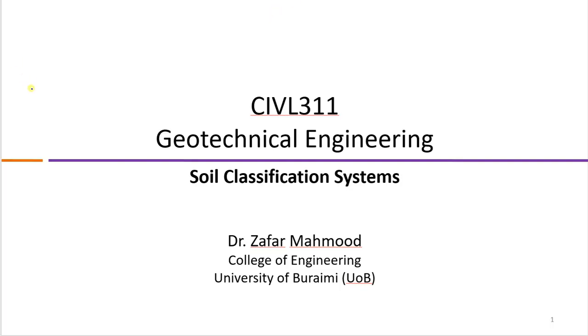Let's start with our lecture today. We are going to start with a new topic, and the topic is soil classification system. In this topic, we are going to cover two types of classification system. One is called the Unified Soil Classification System, and this is sometimes also called the ASTM classification system. This is one that we are going to study, and number two, we are going to study the AASHTO classification system.